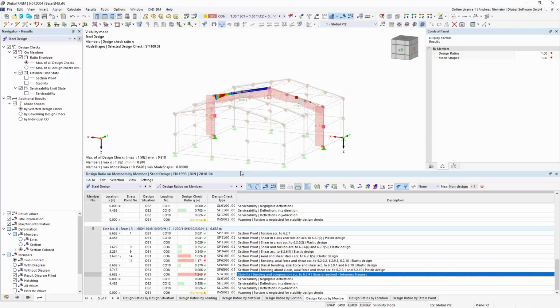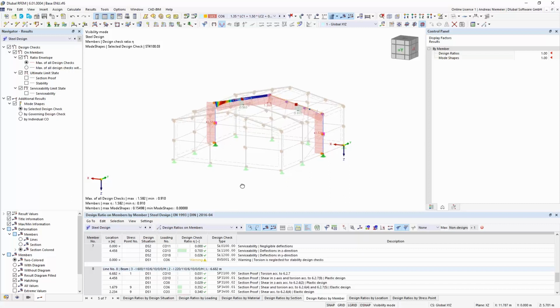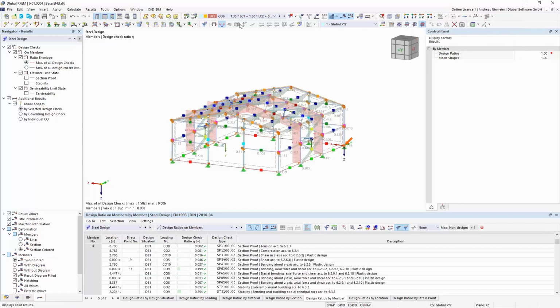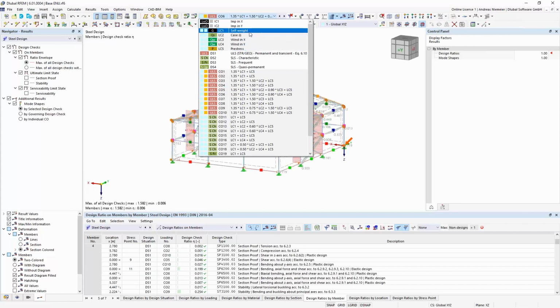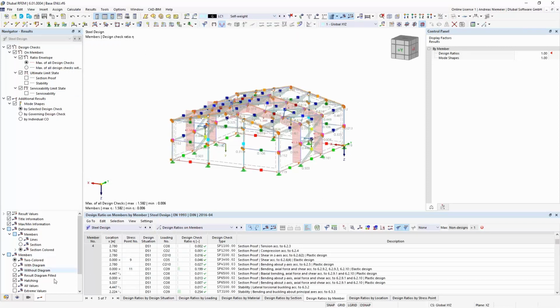And if you want to go ahead, after, let's say, you checked all cross sections and you changed them and you have a green design, then you can go to the documentation and presentation for the customer. Here our program offers some more features. Maybe what is interesting and nice, if you have to, for example, present your customers the deflection of self-weight, we go to static analysis.